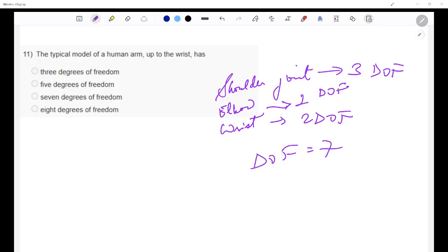This is important, and it is the reason many robotic manipulators mimic the human arm. Industrial robots usually have 6, but the human arm has 7. Thus, the human arm is redundant for positioning tasks. To specify pose in space, we need 6 degrees of freedom, but we have 7. So we have one redundant degree of freedom.